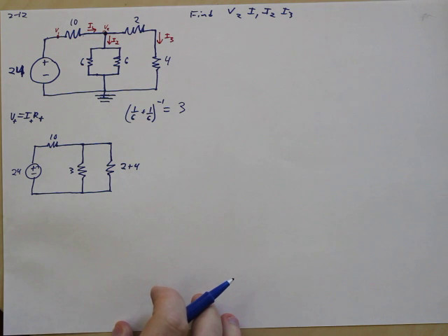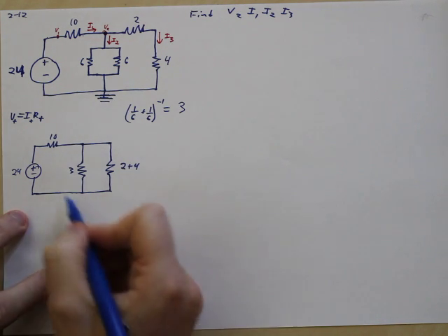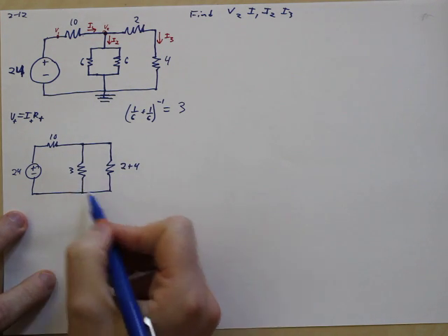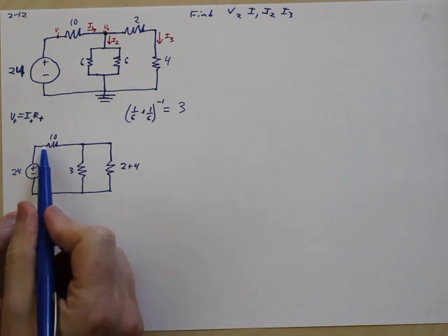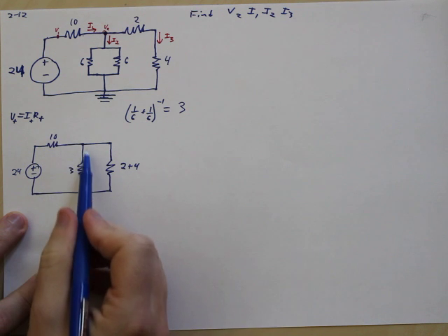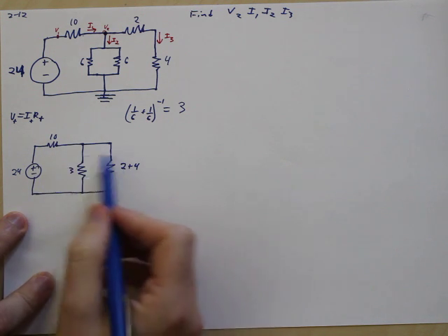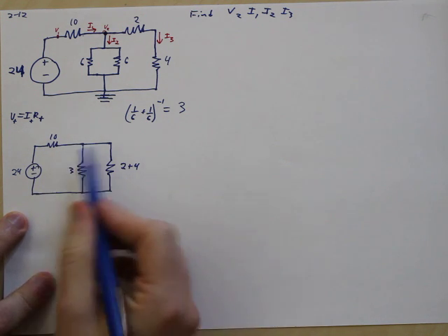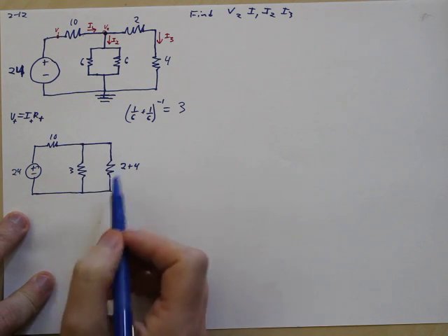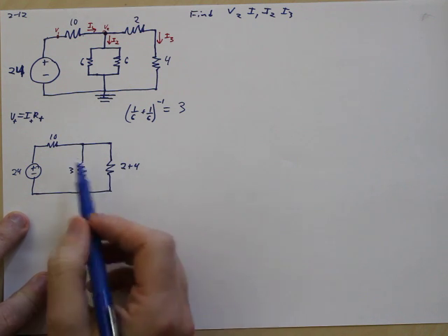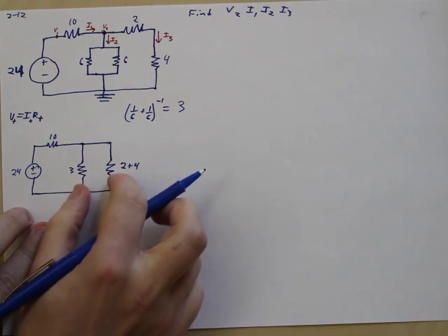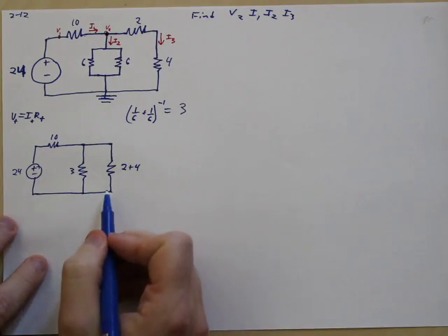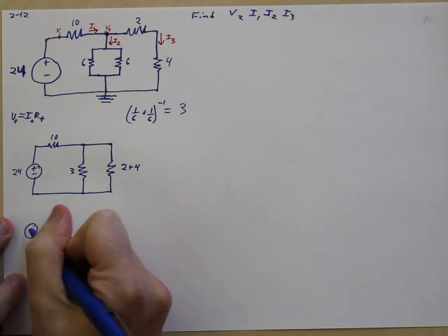And then if we look again, what do we have? These two are in parallel and this one is in series with both of these. So why can't we go right down here and say, hey, this one is in series? Well, it is in series, but this one also has something first. Think of order of operations, like if you have parentheses around it, you need to do that part first. There are imaginary parentheses. You have to add these parallel ones up before you can get the series. So let's do that real fast. We're going to draw another one here.